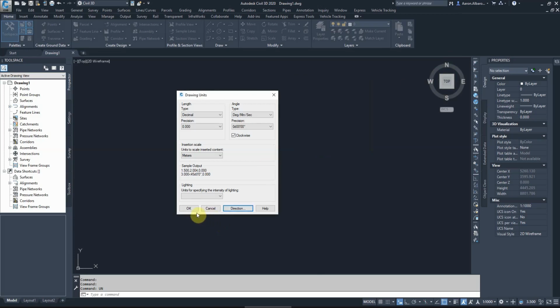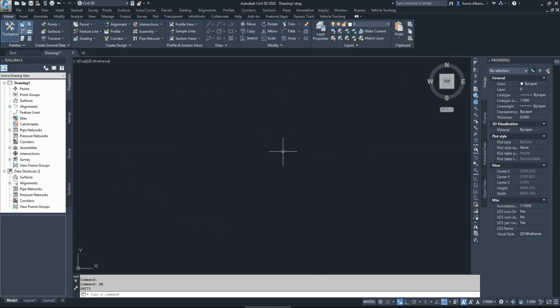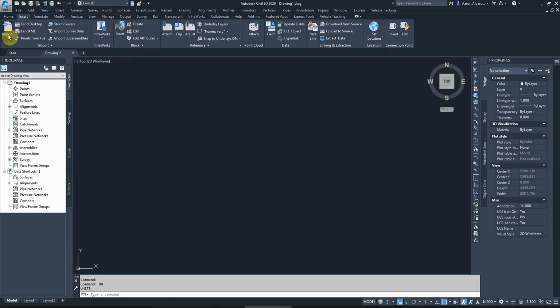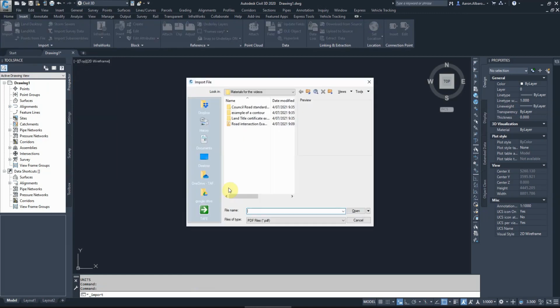And I'll go okay. There we go. So I've got this information sorted. Now let's say I've got that PDF. How to insert a PDF into AutoCAD? Go to insert, or you can go from here, insert and import. Especially on the new versions of AutoCAD and C3D, this will import it into lines and polylines. We didn't have that capability before. It's a great feature, so I take advantage of it, guys.